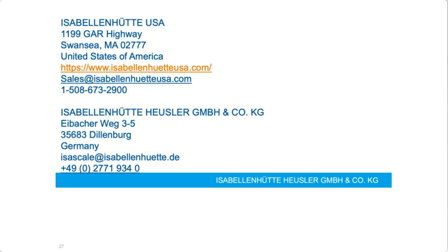Does IEC 61508 cover commercial vehicles up to 40 tons? Yes, thank you for that question. That's a very good question. ISO 26262 is actually an adaptation of the IEC 61508 standard, so it is based on IEC 61508. As I mentioned during the presentation too, officially, this standard was not developed for commercial vehicles, but we can see a trend in the industry that it is more and more used for commercial vehicles.